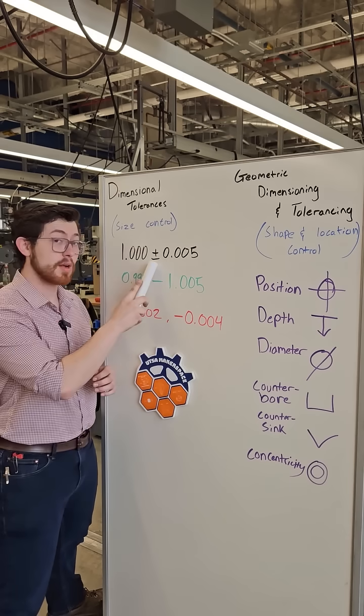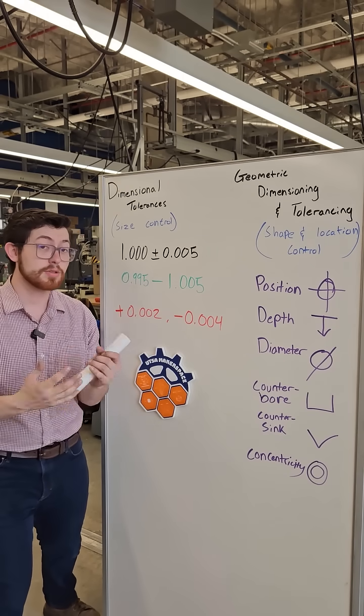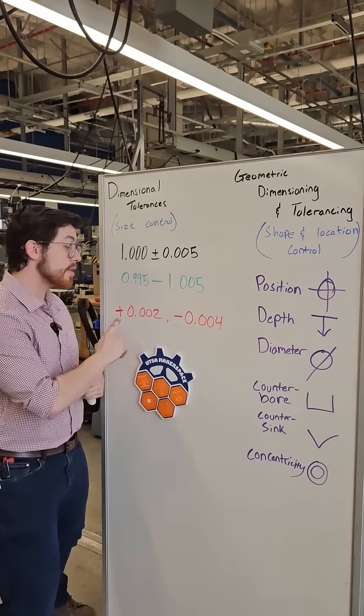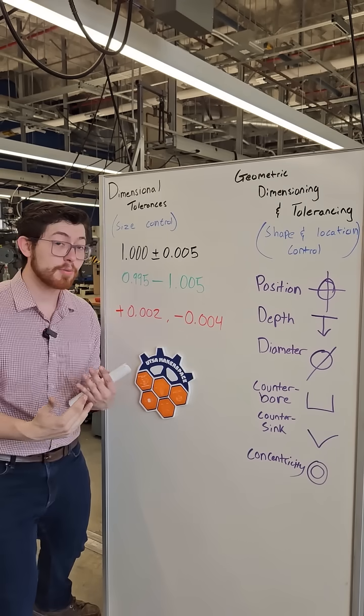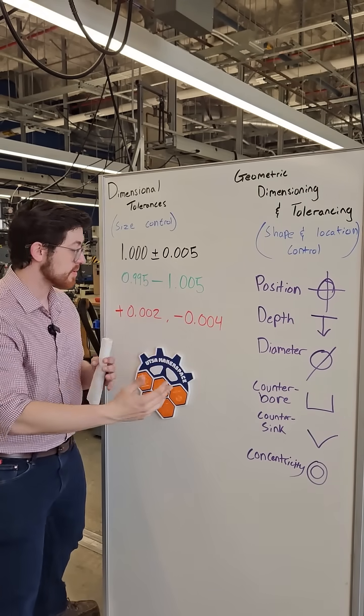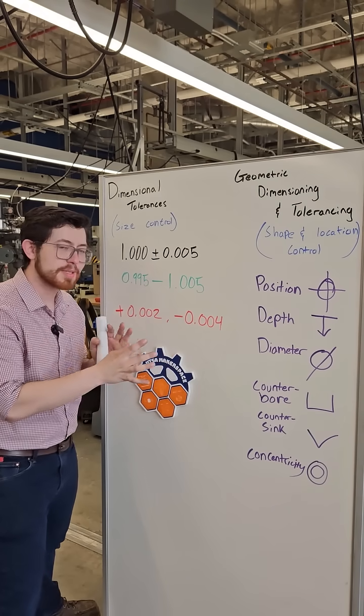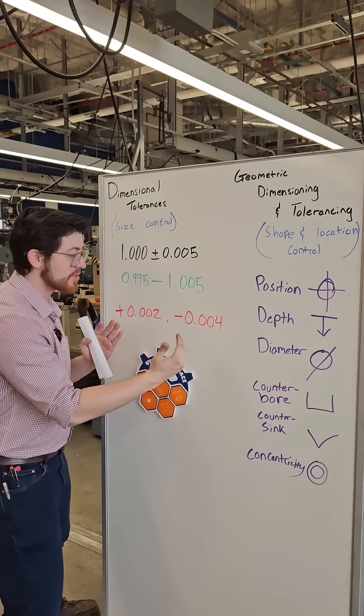And that's a symmetrical tolerance, plus, minus, but they don't always do that. Sometimes they're asymmetrical. Hey, you can go above by 0.002 or below by 0.004 or 4/1000th of an inch. Sometimes they're just hard limits, where you just can't allow symmetrical tolerances.